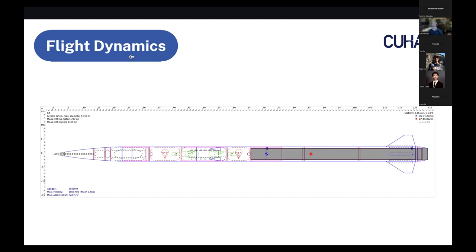Yeah, I don't know if I already told you this, but I forgot where the Malaysian team got them from last year, but one of the rail button products out there is pretty flexible, and in the heat of the sun, I think they over-torqued the screws and it actually kind of squished the rail buttons, and they didn't know about it until it was time to load the rocket on the rail. The rail buttons were squished and wouldn't enter the rail. Wow. Thankfully some of the guys out there had extra rail buttons, so we quickly swapped them out.